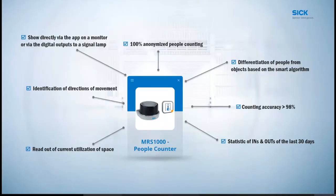So what we ended up with is what's called the people counter, which is a LiDAR-based sensor. If you're not familiar with LiDAR, it basically uses lasers to do distance measurement. And then based off of what those distances are, well, like I said earlier, we can do a wide variety of things. In this case, we look at those distances and basically determine what is a person and what is not. And then we determine the direction of the person and basically use that to increment a counter. So we'll talk about that a little bit further, but these are just some of the main benefits of the people counter.